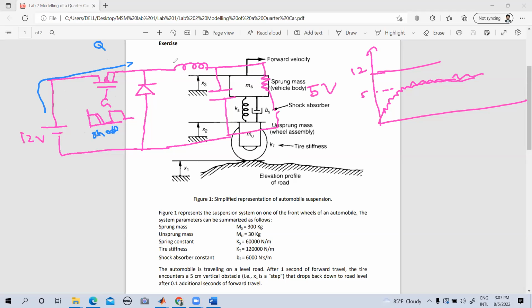If you take the positive and indicate the polarities, it's going to be positive, negative. There's no current through this. The load resistor, there's going to be current like that. We can apply Kirchhoff's voltage law and KCL at this particular node and find the values. You can find the inductor current. This is IL.